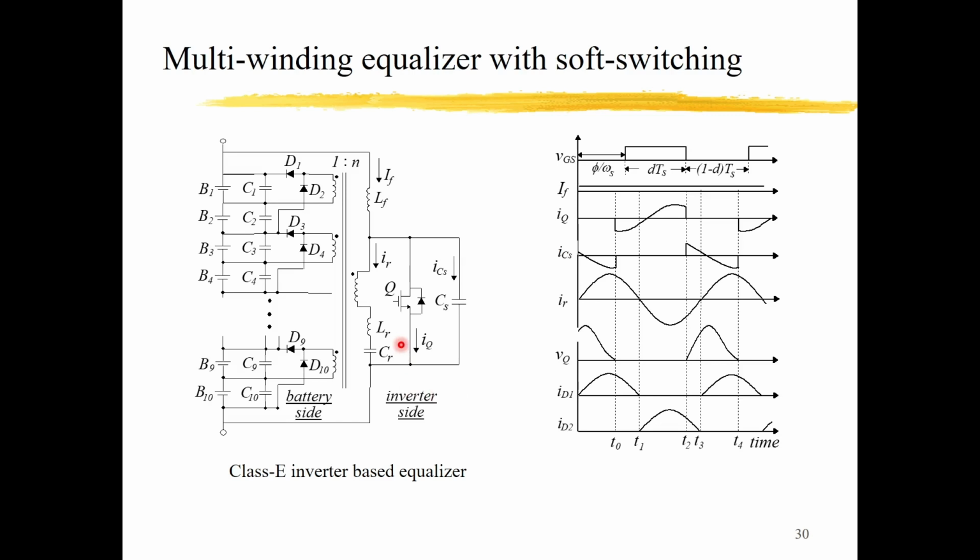It is a converter to transfer DC signal to AC signal, so it is an inverter, and it takes only one switch to fulfill the inverting function. Usually we need two or more switches to achieve the inversion, but Class E takes only one.